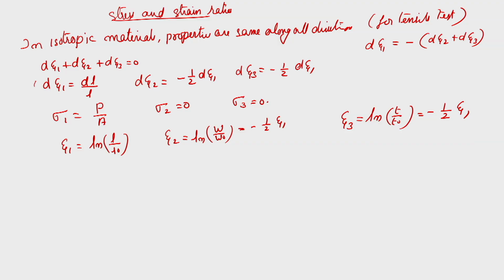So, maybe I can write that, since the two principal stresses are 0. In typical sheet metal processing, most elements will deform under the membrane stresses sigma 1 and sigma 2, because that will not be equal to your uniaxial tensile test.